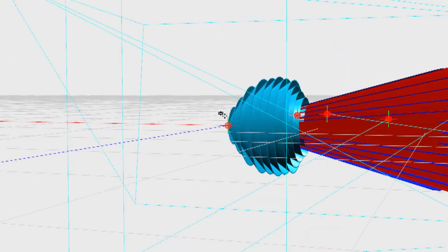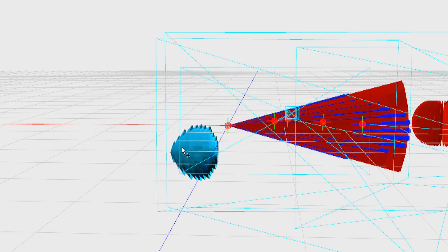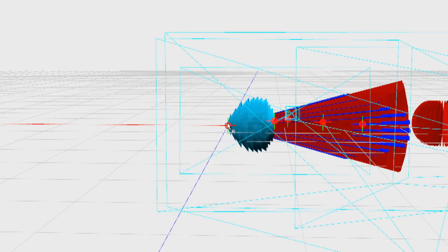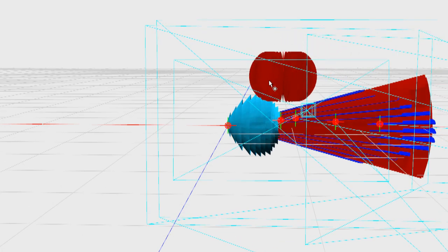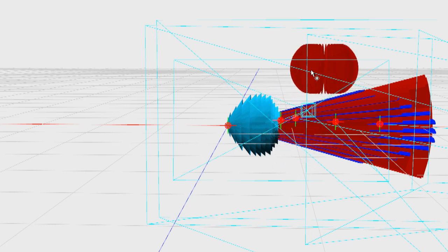In addition to that, you would also perhaps have a circularly polarized antenna, which in close range flights, when you're coming back into land, would always give you a solid signal, even if you were coming on your final return through some trees, for example.